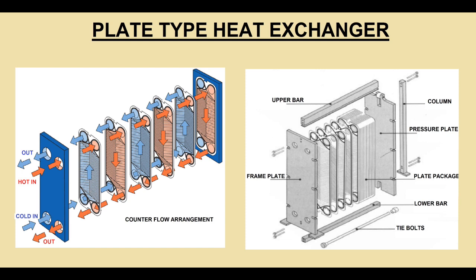When the package of plates is compressed, the holes in the corners of the plates form continuous tunnels, or manifolds, through which fluids pass, traversing the plate pack and exiting the equipment. The spaces between the thin heat exchanger plates form narrow channels that are alternately traversed by hot and cold fluids, and provide little resistance to heat transfer.